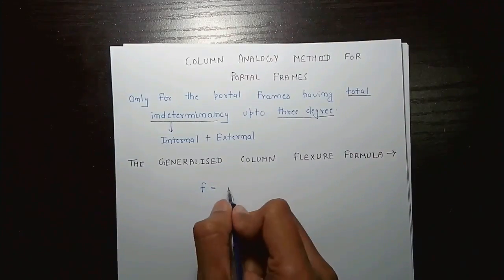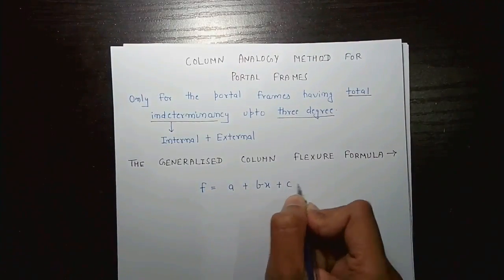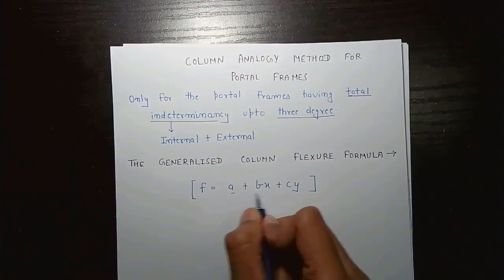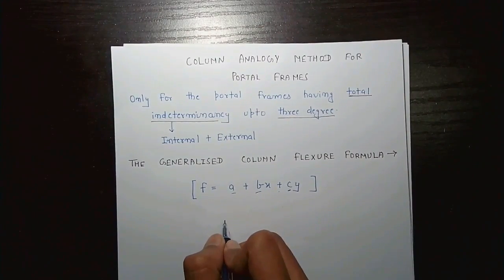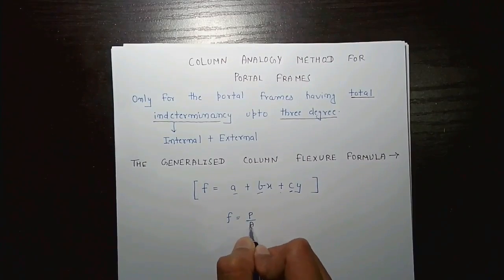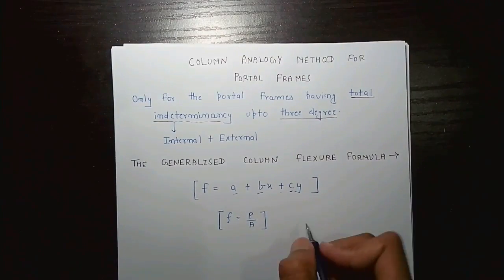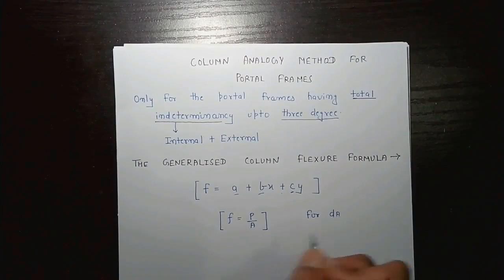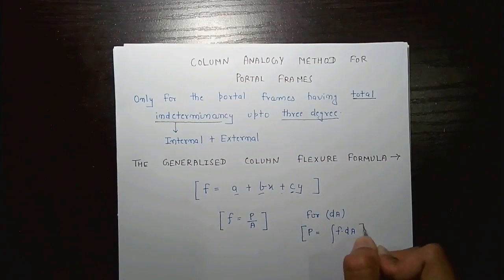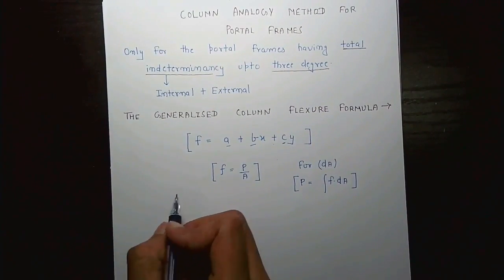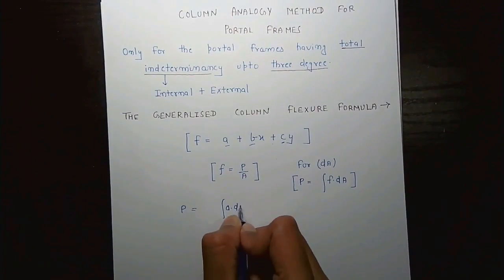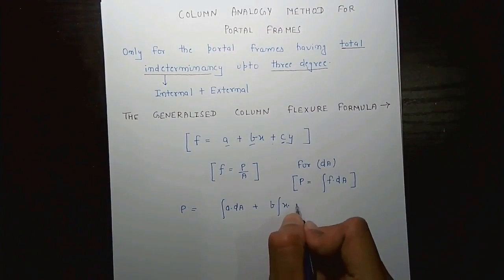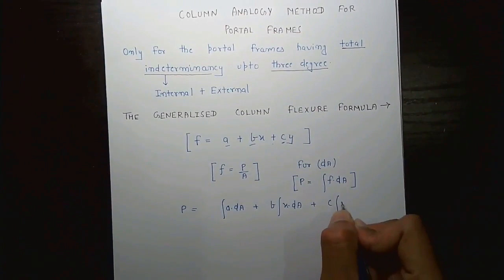Let stress at x, y be f equals a plus bx plus cy, where a, b, c are arbitrary constants. Now we know that stress is load per unit area, and for small area dA we can write load is integration of f dA. Now by this equation and this equation we can write load is this.